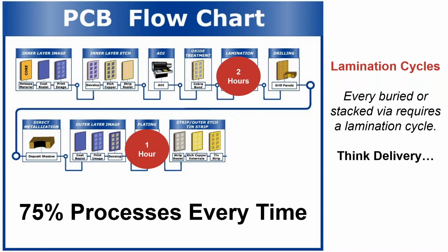And when you come into plating, it basically takes an hour to get through the entire process in order to meet the IPC specifications, to have the whole wall meet the specifications required by having enough metal actually deposited. So this is what we talk about when you add cost to it, and you wanted to know why. It's because you're having to go back through a whole lot of the processes several times.